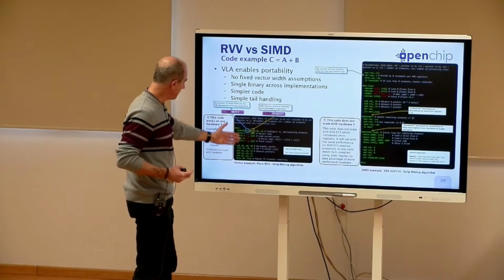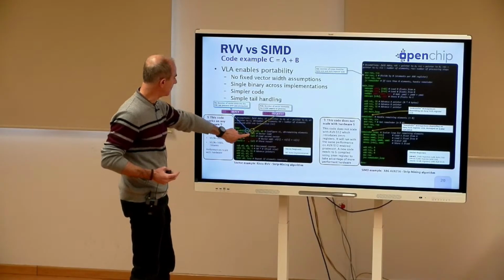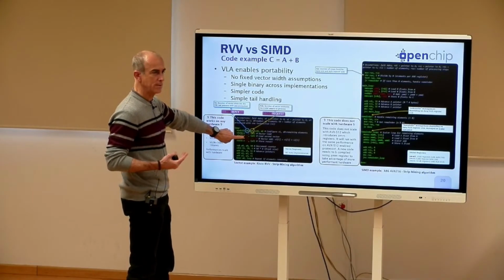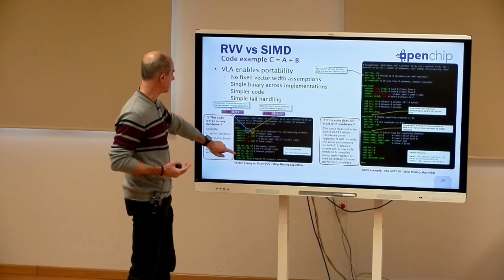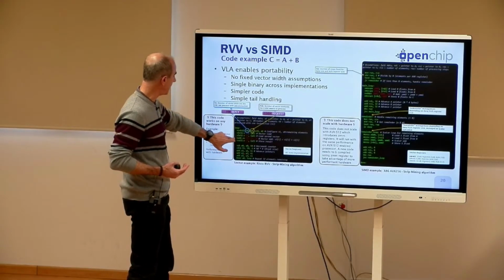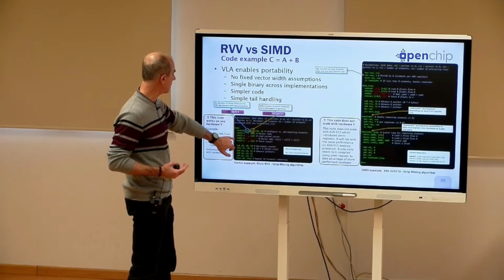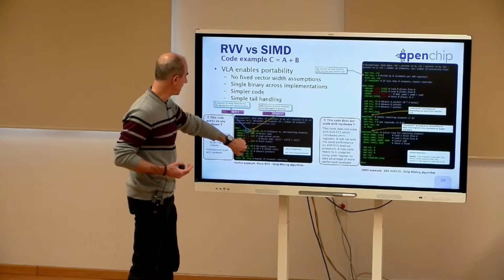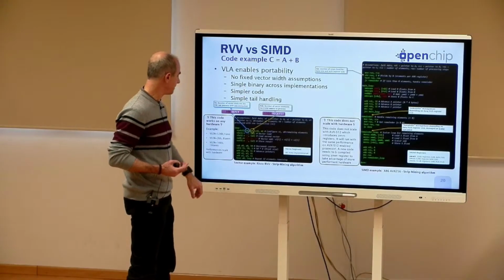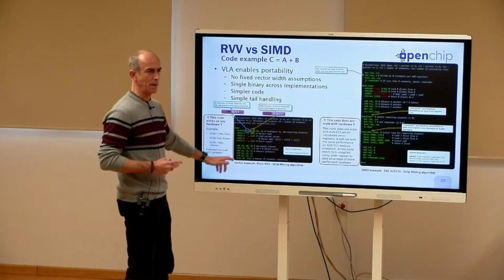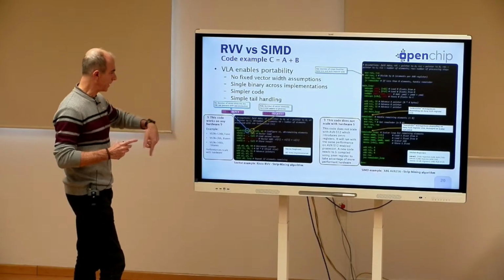And then there are very few instructions. Two instructions here to load v1 and v2 from memory. These are the pointers to memory. Then this is the add operation. You want to sum v1, v2 and put the result in v3. And then you store back the result in memory. These are the instructions to update the pointers in memory to do another loop.